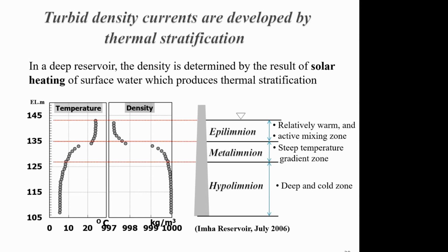How far up can it go? Up to what concentration can I go so that everything would have the same density, right? Well, it's 2.5 times 1,000 to bring this into milligrams per liter. It means that, grosso modo, as an order of magnitude, you could have 2,500 milligrams per liter of fine sediment added to your clear water on top, and the water would still have a density less than the cold water underneath. Does it make sense?